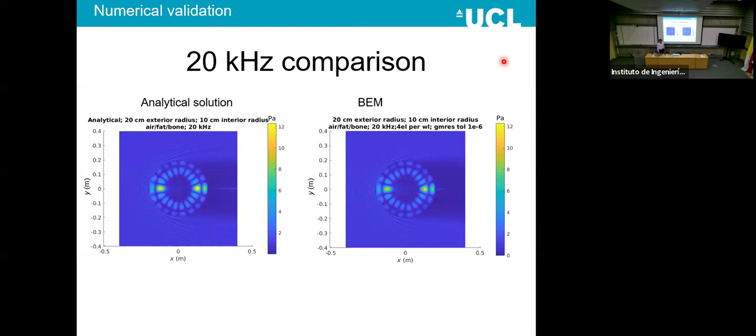What boundary condition were you using outside? Oh, I think we tried a range. We tried initially FEM-BEM coupling that just wouldn't converge. We tried, I think, a Robin condition. Do you remember what Ganesh used in the end? He tried a number of things, but essentially, you get it to work at low Ka. As soon as you got higher up in the frequencies that we wanted to look at, it would just break down.